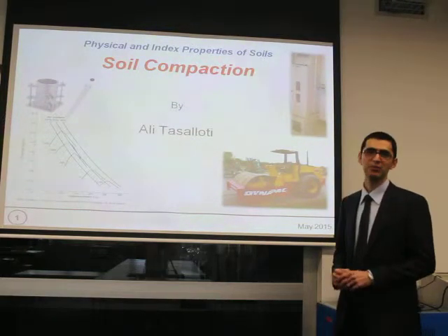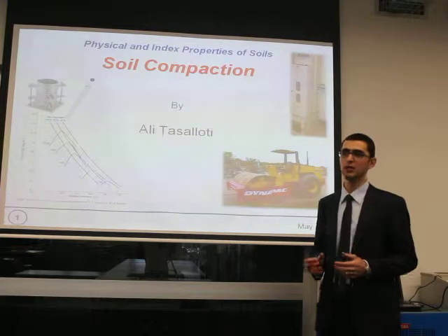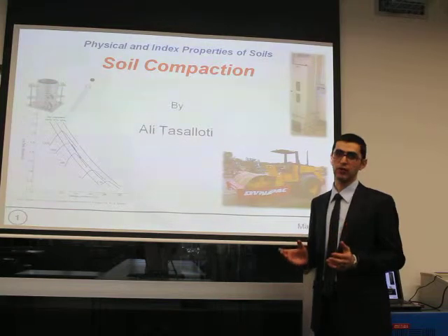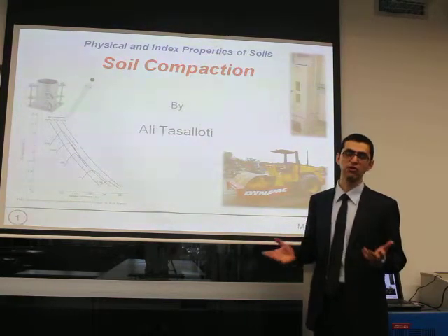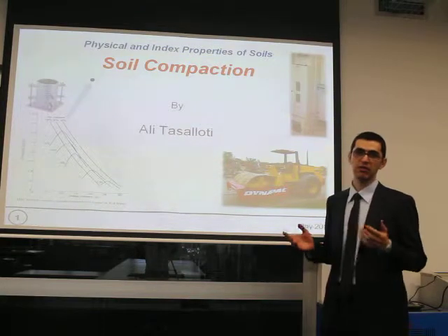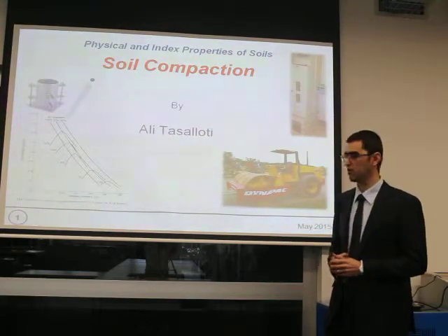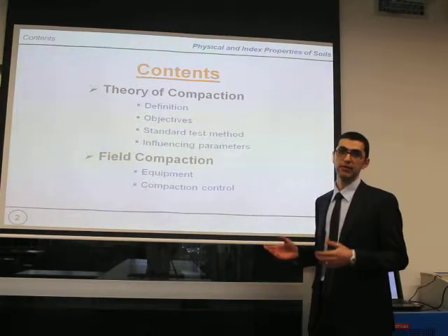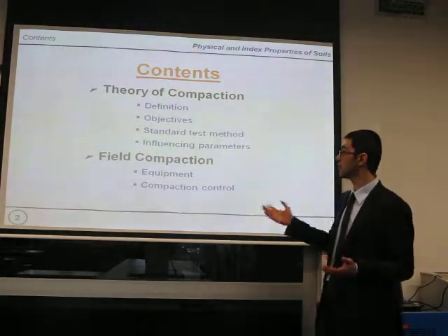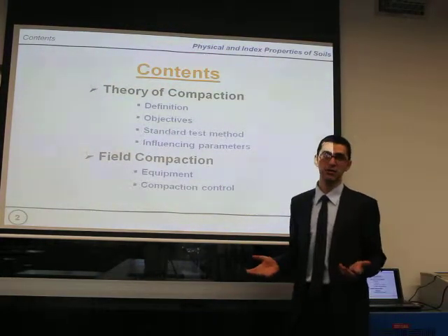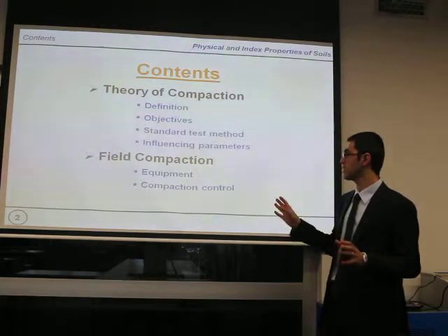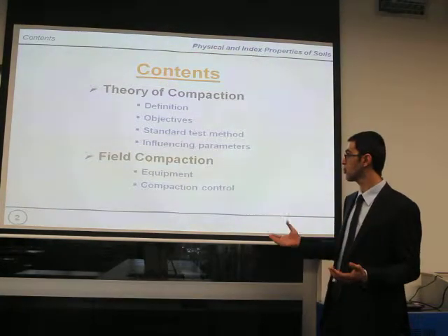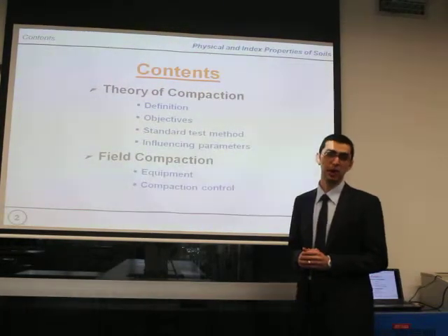Hello everyone. In the previous lecture we studied the physical and index properties of a soil. Today I'm going to introduce you to soil compaction as another geotechnical property, and we will understand the compaction characteristics of a soil. In the outline of my lecture, I will go through the theory of compaction, covering the definition, objectives, standard test method, as well as briefly the influencing parameters, and next week I will explain in more detail about those parameters as well as compaction in the field.